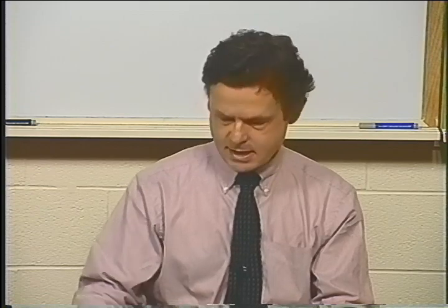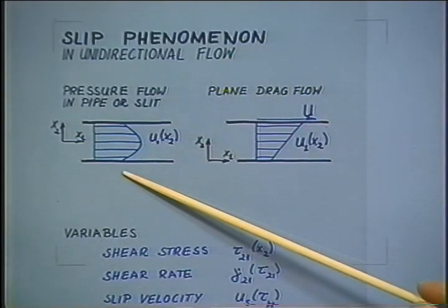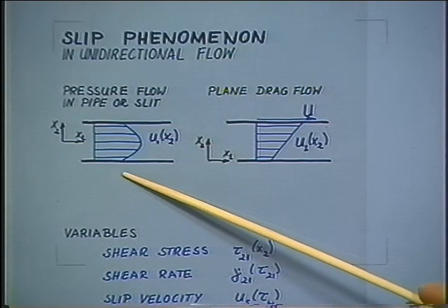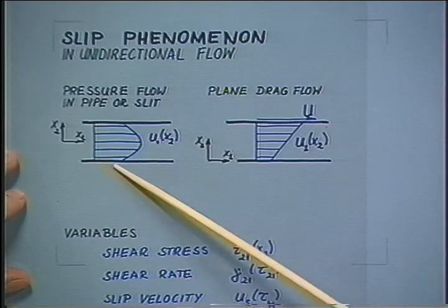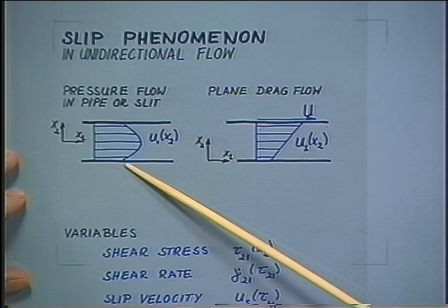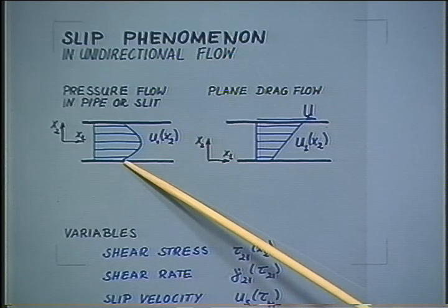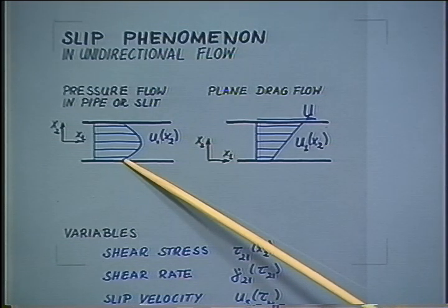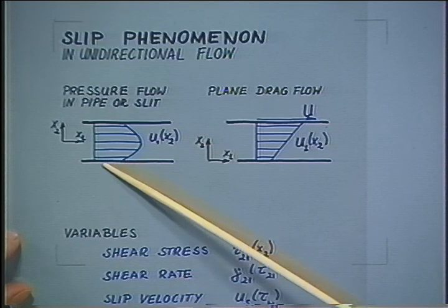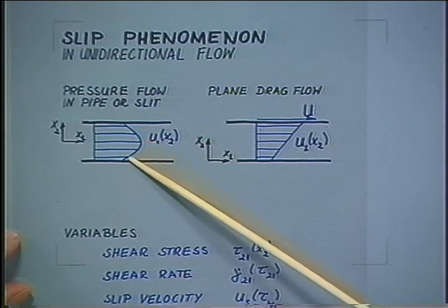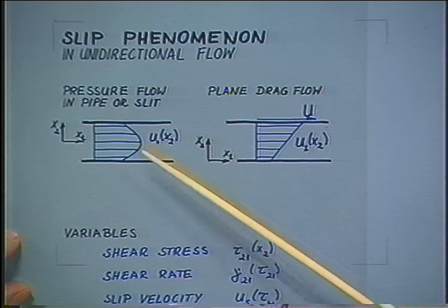And here I sketched a graph in front of me. The polymer, when, for instance, pushed through a channel, is sometimes sliding along the wall. It's not at zero velocity or at the velocity of the wall. There's a jump in the velocity. If you would have a solid sitting on a wall and you push that solid, it would go from zero velocity to the full velocity immediately. But in our case, in the liquid, we have the jump of velocity, and then on top of that, the liquid is deforming, so it's also in between.